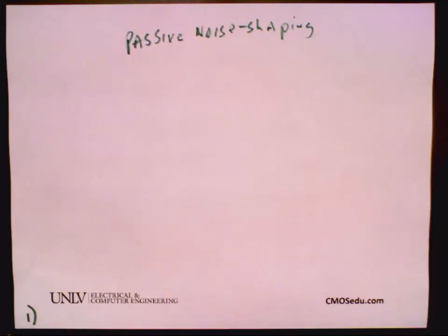Wait, the DAC should go from 0 to 0.875 of 1.125 volts. So you should be able to go 0 to 0.875 on the input. Yeah, that makes sense. If you put above 0.875, it's going to give you a tone out because it's always going to be saturated and railed. Does that make sense?